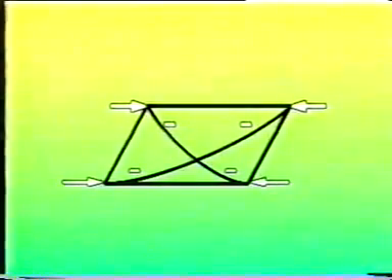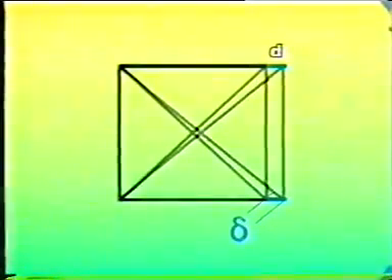How can these additional forces be calculated? One bay of a bridge is considered. The vertical loading elongates the main girder at the bracing level by D. The wind bracing should follow this deformation completely, as the influence of these components on the total bridge behavior is negligible. The displacement D is compensated by elongation delta of the member of the wind bracing by means of an axial force.